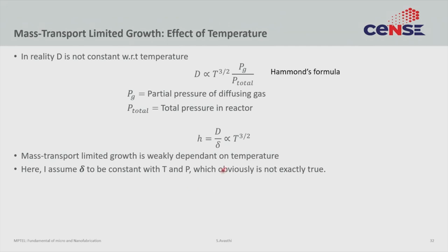So is this formula exactly true? Probably not exactly. But in general, reactions tend to practically show this. There are a lot of second, third order effects that happen, so it's very hard to give exact exponents. The take home message here is that there is some weak polynomial dependence. Whether it is 3/2 or 1.6 or 1.8 or 1.2 really depends upon the details, but there is some weak polynomial dependence of Henry's constant on temperature.